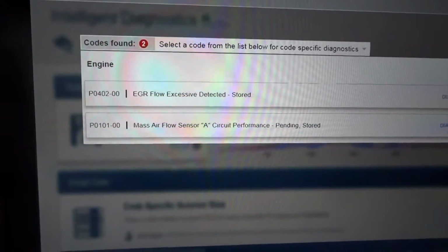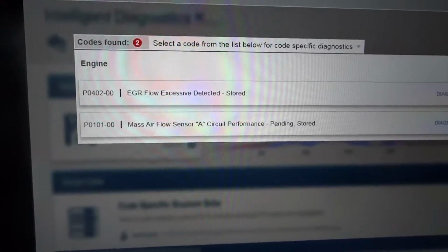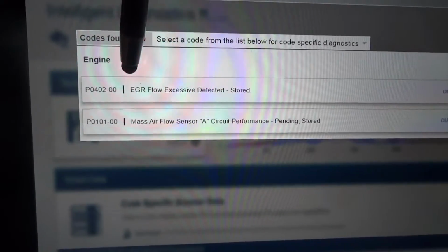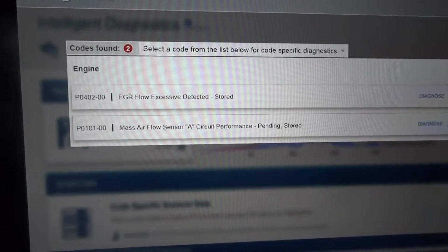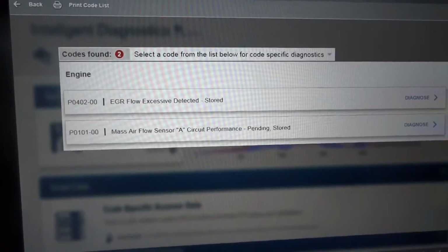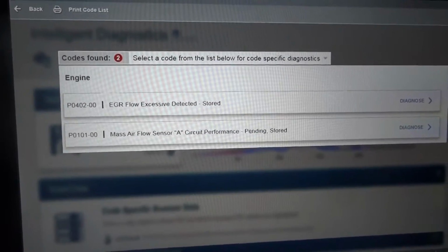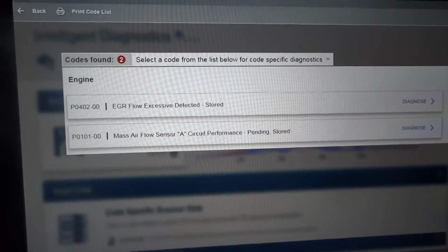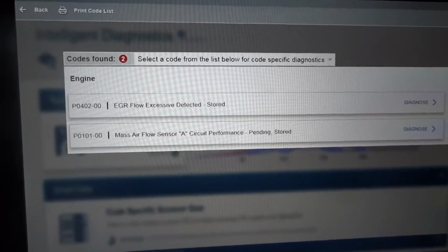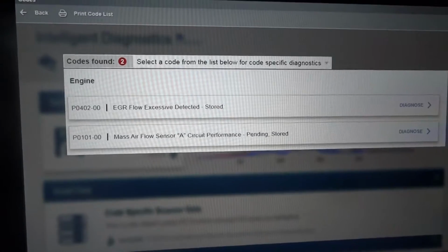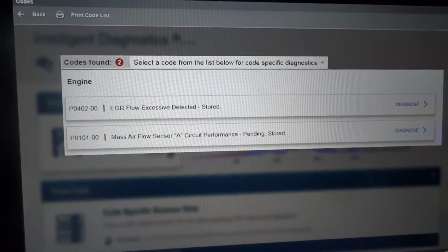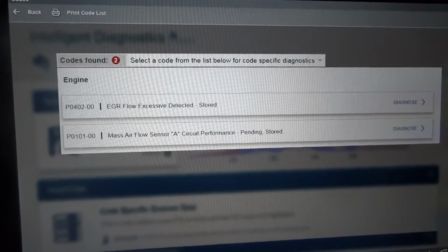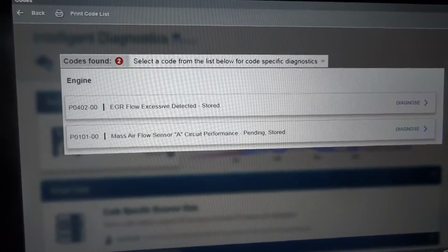If you have a question about what the EGR is, EGR means exhaust gas recirculation. We have EGR systems in vehicles to reduce the formation of NOx. Okay, NOx is not a good gas. NOx causes a lot of problems, so to reduce it, we have installed EGR systems on engines to reduce the temperature of the cylinders, to cool down the cylinders a little bit.